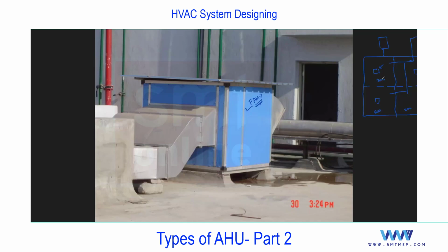The total CFM of this room, say 3000, for example, out of which say 10% means 300. Now, the percentage I'm using just as a thumb rule. We have a separate calculation for this. So this FAHU is responsible for providing the requirement of fresh air. And FAHU means AHU, in that you'll find the cooling coil. Definitely it is going to be treated, meaning cooled fresh air, right? So the same FAHU, if I use it to provide fresh air, and there is no return duct.